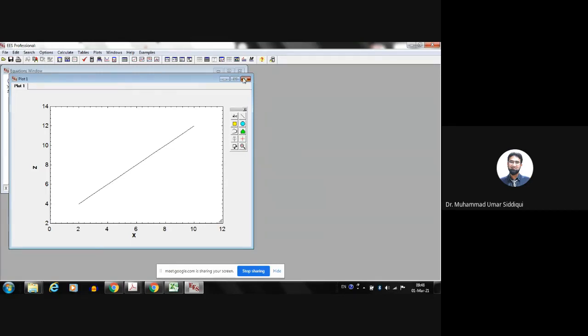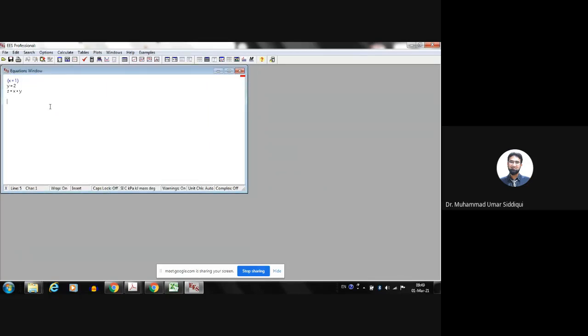Okay, like for example, if I want to write the first law of thermodynamics here, we studied the first law of thermodynamics. Okay, Q minus W plus E_mass_in minus E_mass_out is equals to delta U plus delta kinetic energy plus delta potential energy. Okay.